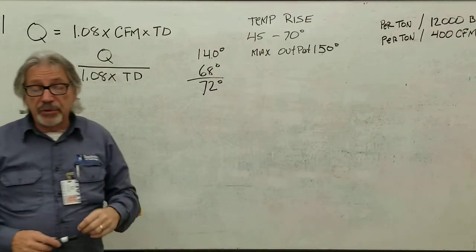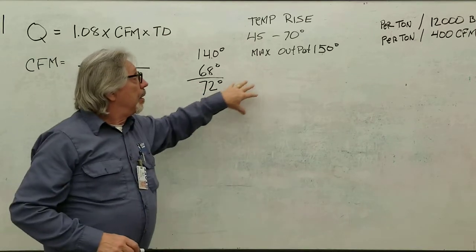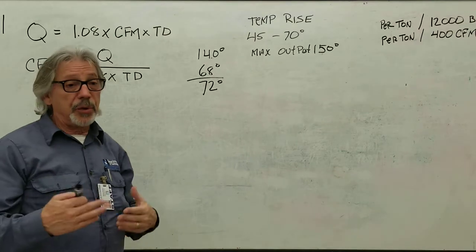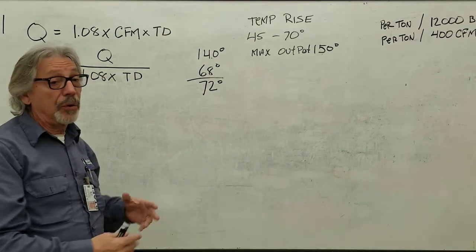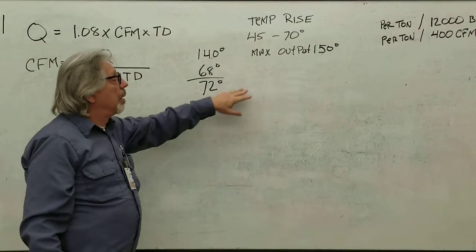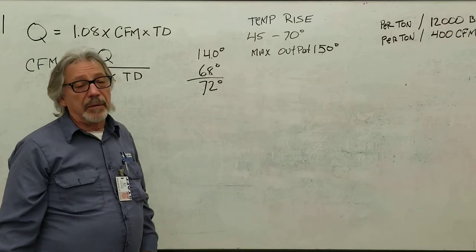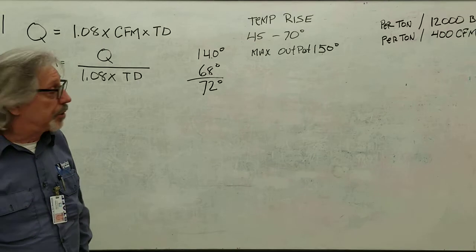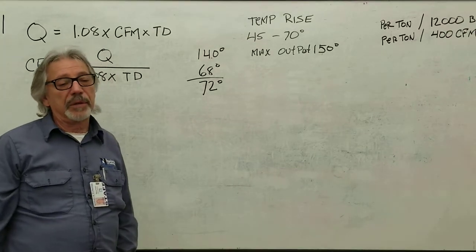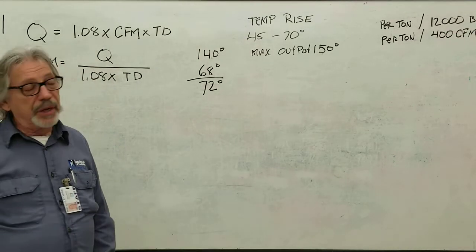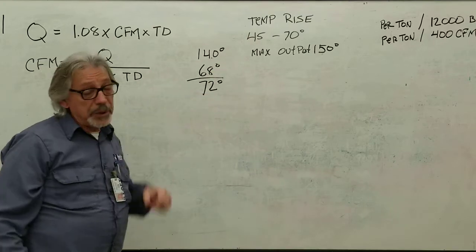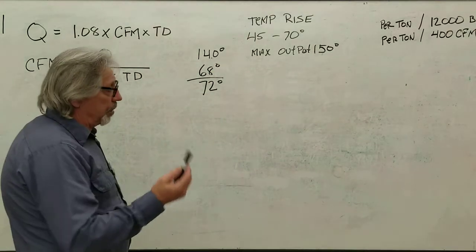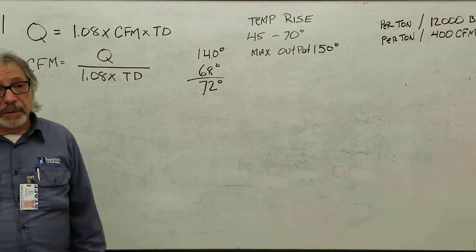One of the issues on this furnace might be the air filter. You're restricting airflow, there's not enough airflow going across, or it's fired too high. Or the gas, you need to adjust the gas pressure to reduce the fire on the furnace. That's one of the important things we do when we check these temperature differences. It's not something we just do because it's in the book.